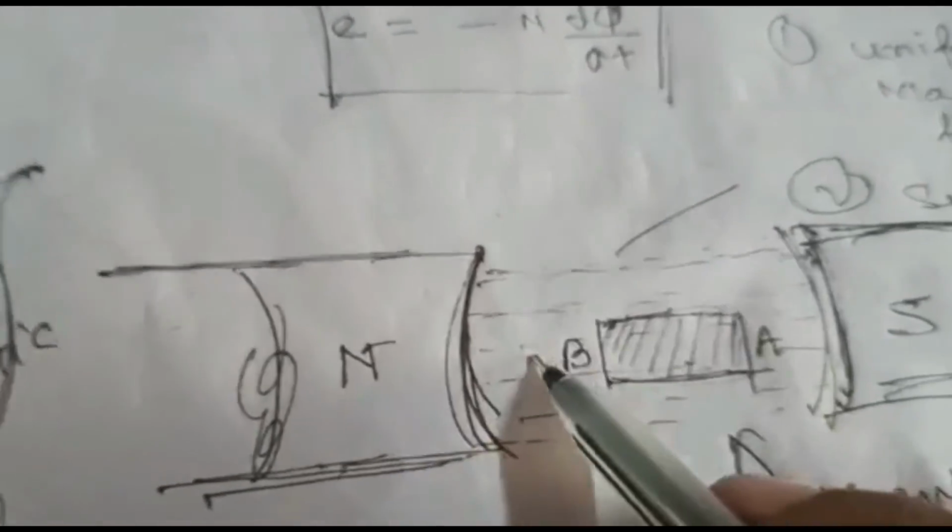Now if AB is rotated in the reverse direction, compared to the previous direction the flux linkage is reduced, then EMF is also reduced. So from here, the voltage starts to reduce. Now at this point, the conductor AB remains horizontal but with opposite polarity, A and B are swapped compared to the previous case, so the polarity changes, and the value remains 0 because it is the rest condition.